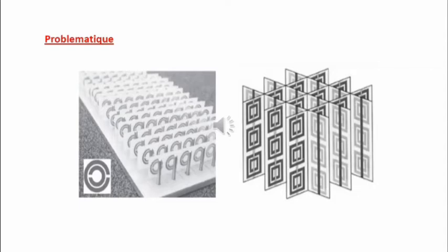In this context, we propose an approach that consists in generating analytical expression for effective permeability, effective permittivity, refractive index, and electromagnetic coupling coefficient for typical split-ring resonator cells from the transmission and reflection parameters.